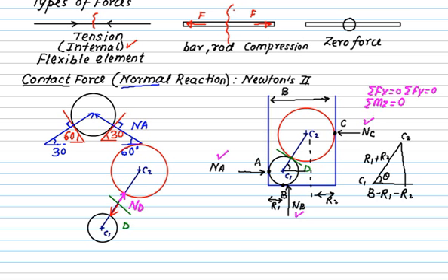But suppose there is one more cylinder here. So an additional reaction will come here in the same problem. I will not show this reaction, but now how many unknowns are there? Let's say this equals NE. So the number of unknowns becomes 4. Is that correct? One is NA, second is NB, one is NC, and the fourth one is NE. Now you have limited equations. That is not going to change. So what will you say? I have 4 unknowns and 3 equations. The problem cannot be solved. So that is why FBD is introduced.